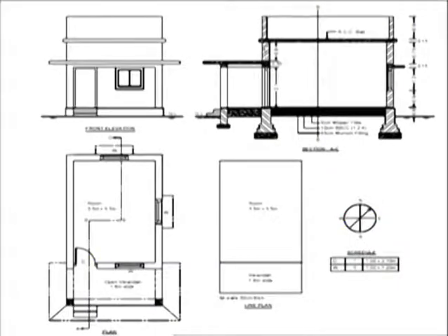It takes the weight of the masonry. In this door or window, exactly above this opening, the masonry is there. If this beam is not provided, that load of masonry will come on the door, and then the deformation or deshaping of these doors and windows may happen.